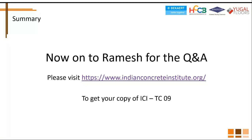So a short answer would be, I would say 600 square meters, and the reason is not the limitation or the ability of the flooring contractor, but the limitation on the supply of concrete. We want to limit pouring to about 5 hours, and on an average of about 15 cubic meters an hour, we are looking at about 75 cubic meters. A 6-inch slab, that is 600 square meters, is about 90 cubic meters.